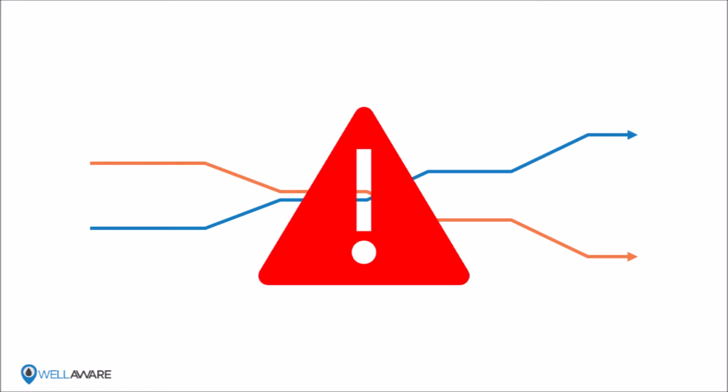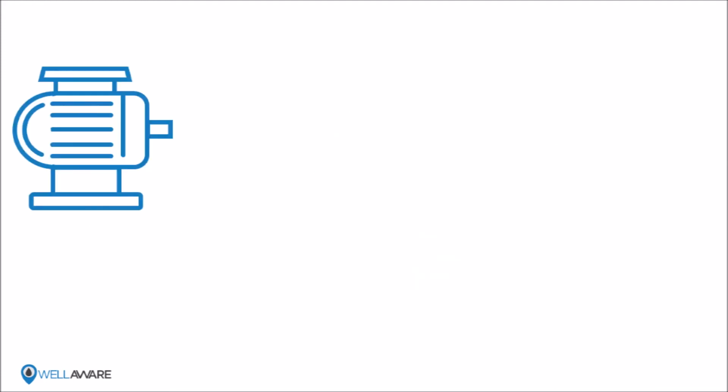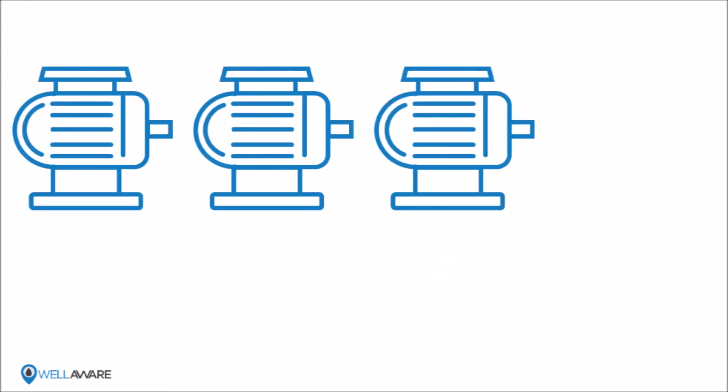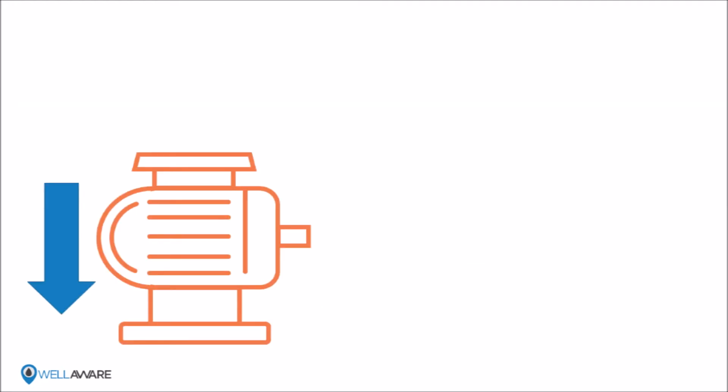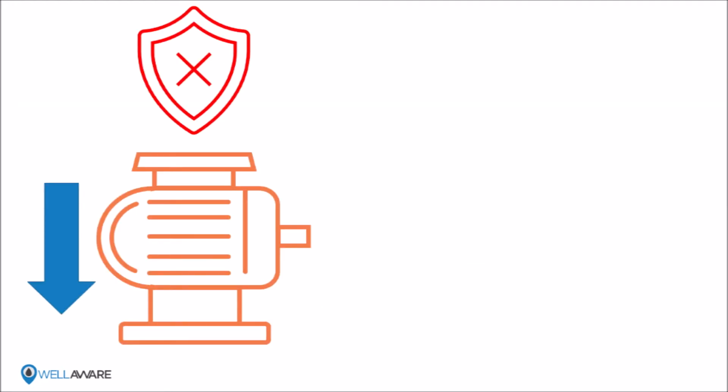In fact, WellAware baseline data collected from thousands of chemical injection sites suggests that 3/4 of pumps miss targets by over 25%. Why is that bad? Well, under-injection is bad because it doesn't protect our asset. If this chemical is designed to do something to improve outcomes or prevent failure, not injecting enough usually means we see poor outcomes or failures.